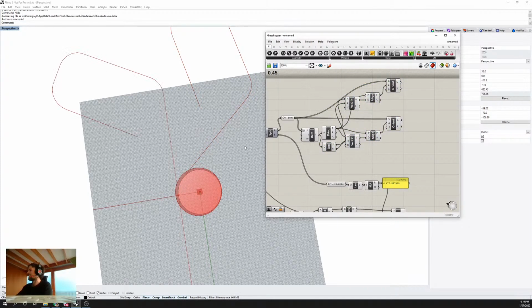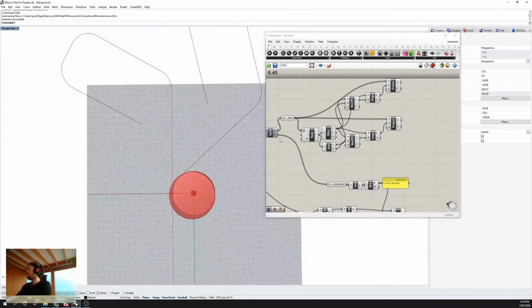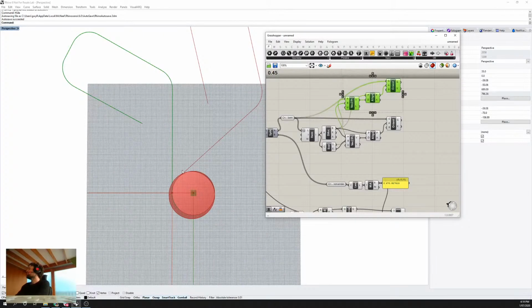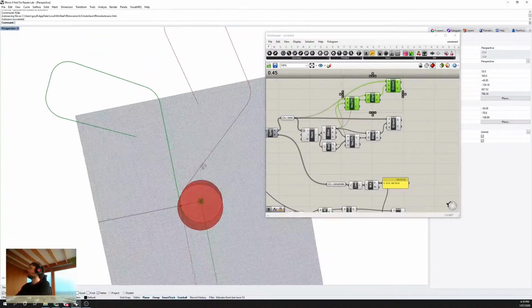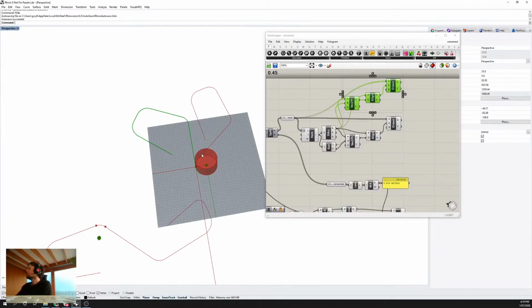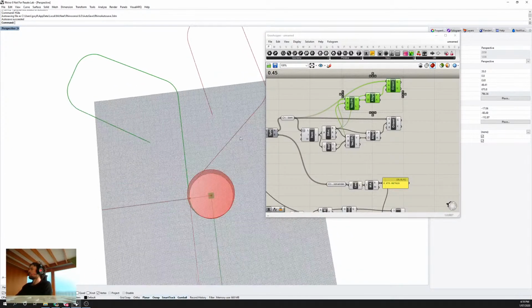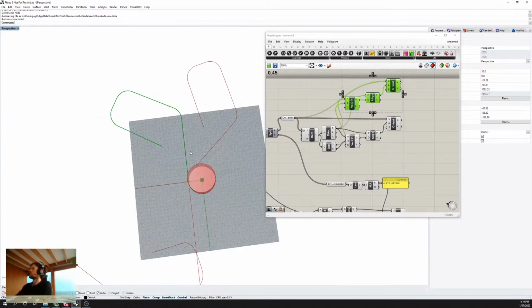Okay, well, that's definitely easier. Let's just do that. So there's two options really for this. One option would be to rotate the part. So we're rotating around or in this bender plane to pull it back so that it lines up straight with our stock material. So that would show us the shape before and after the bend.